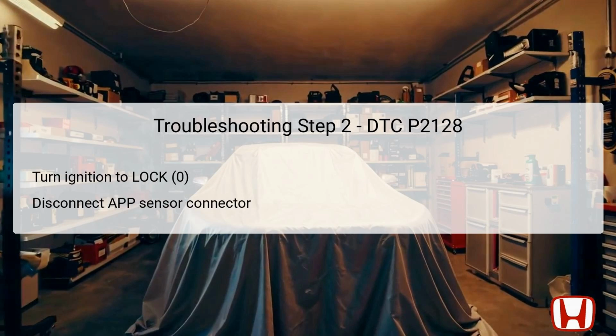In the second step, turn the ignition switch to the lock position, which ensures that all electrical systems are completely powered down. Next, disconnect the APP sensor's 6P connector to access its terminal connections and begin voltage testing. This step is critical in isolating the APP sensor from the vehicle's electrical system, allowing for specific measurements without interference from other components.